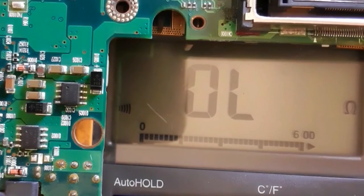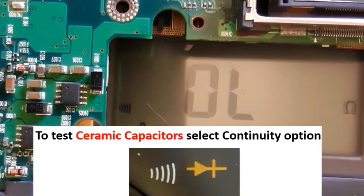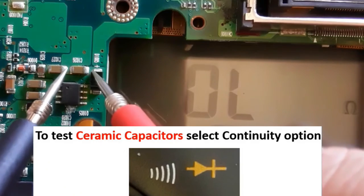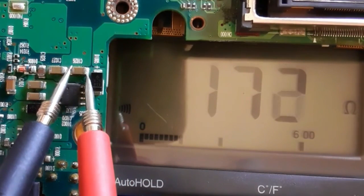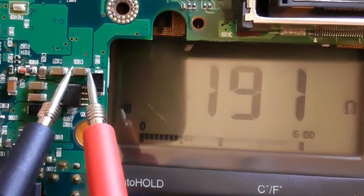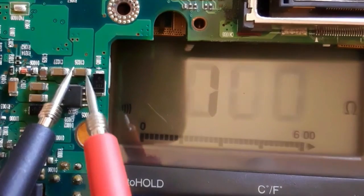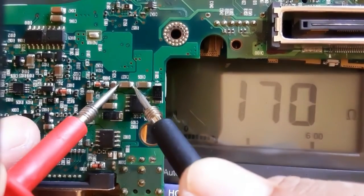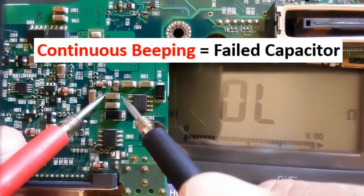So now let's check the ceramic capacitors, okay? Using the same working principle, you should get a value in the multimeter. The value increases, as you can see. We get a value, which means the ceramic capacitor is good. If you get continuity or a buzzer, it means the capacitor is damaged, is bad.